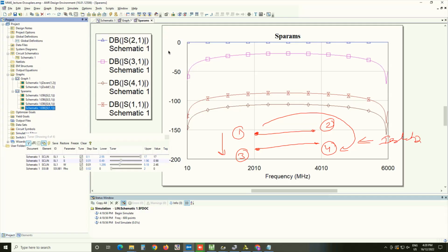If you remember, I had told you that it's called a directional coupler because of the preference in where it couples the power. We talked about using it for doing reflection measurements, to separate waves propagating in two directions. And the way we had done it is by putting some device at the end of port 2.